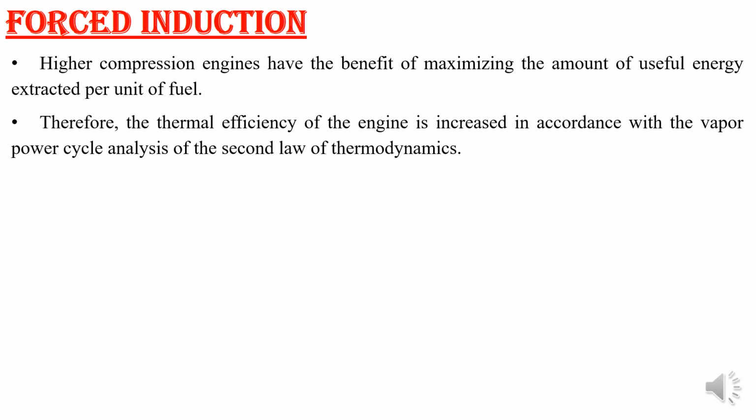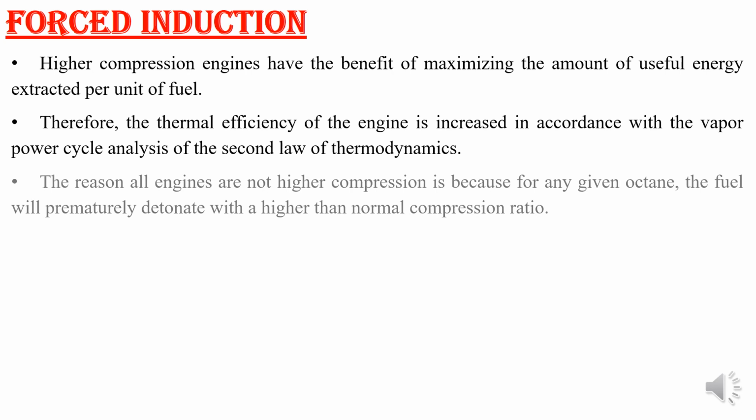So that is the main advantage of the supercharger or forced induction system. In such cases we can use the engine at a higher compression ratio, but the problem is that knocking may come into the picture.